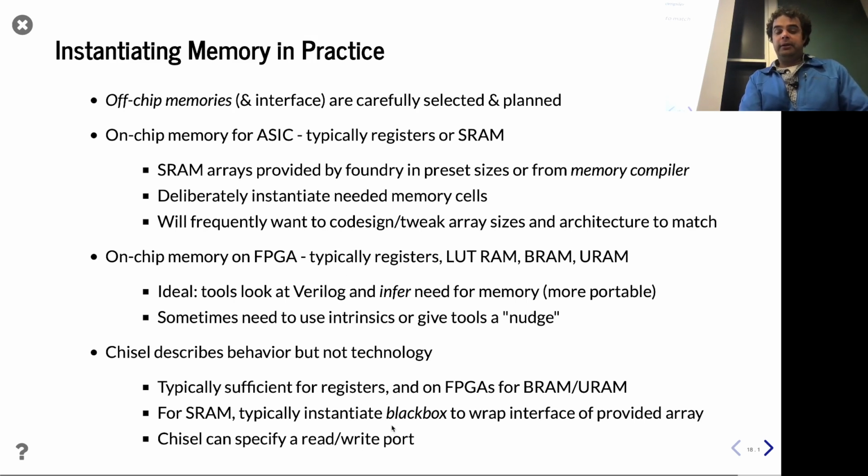When it comes to Chisel, you actually can use a command line flag called externalize mems that will generate stub modules, so it's easy for you to go ahead and use another tool. Rather than instantiating the memory, it generates the Verilog as a module, like a black box, that can be replaced by the memory. Depending on what version of Chisel you're using, it actually gives you a JSON file, which you can feed into some other tool to get the memory you want. So it tells you, here's the memory module, you need to make a Verilog file that has that memory module, and here are the parameters it has: it needs this many ports, this latency, this capacity, etc.